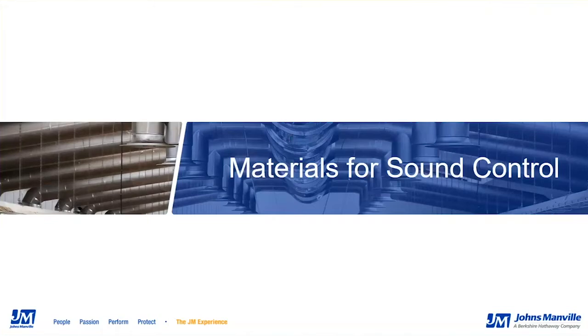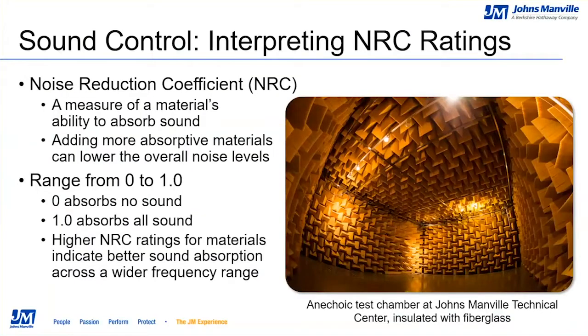insulation to tackle it. A common measurement presented for acoustical materials is the noise reduction coefficient, NRC. This is a measure of a material's effectiveness in absorbing sound in a space and is measured according to ASTM C423. It's an average across 250, 500, 1000, and 2000 hertz performance. The NRC is in place, like an R value, to help give us a unit of measure with which we can compare the acoustical performance of various materials.